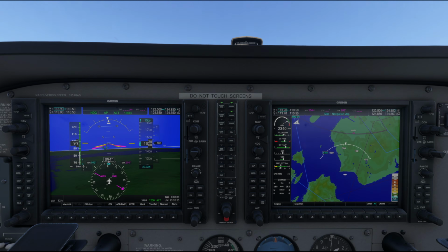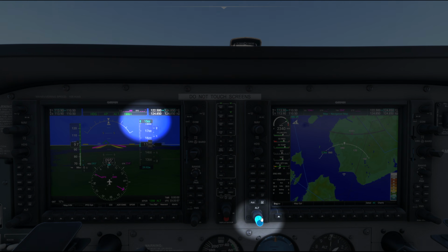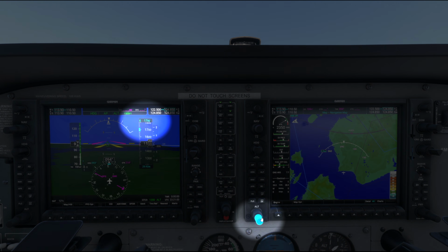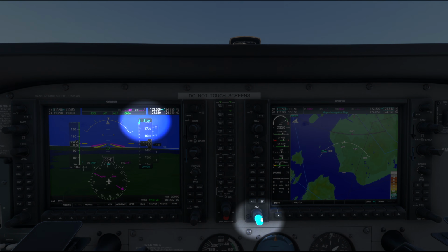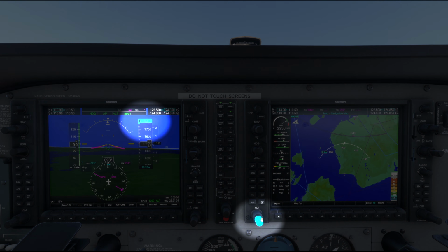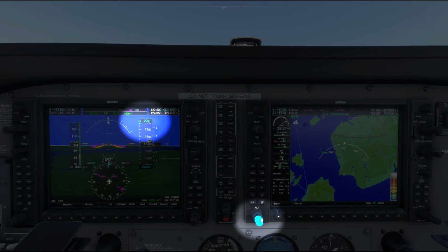In this mode, we choose the climb rate in feet per minute rather than targeting a specific airspeed. This is useful because you typically want a fairly gentle climb or descent rate for passengers, usually in the range of about 400 to 600 feet per minute.